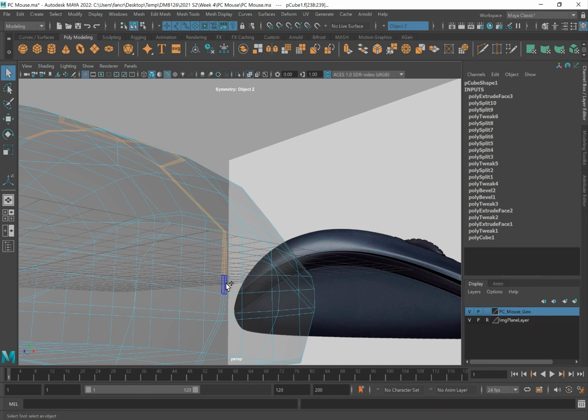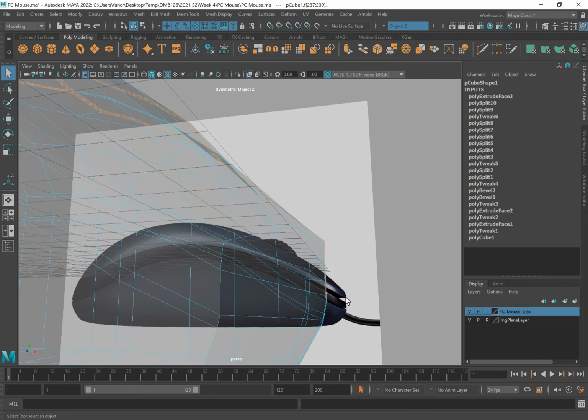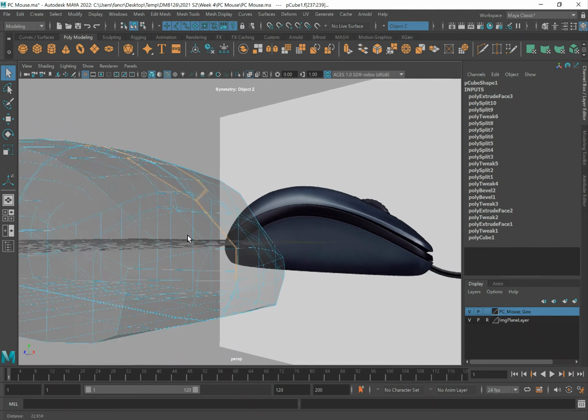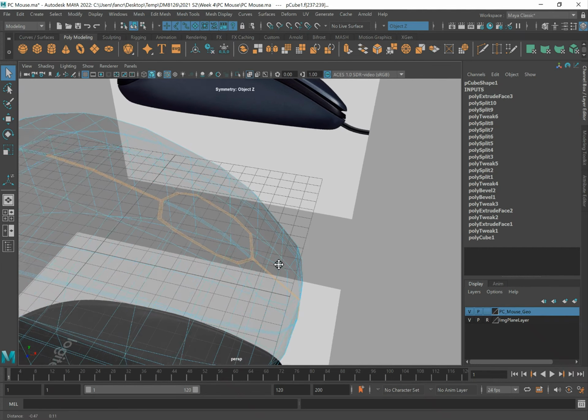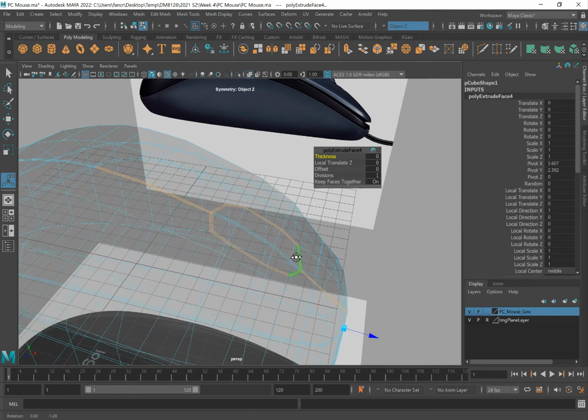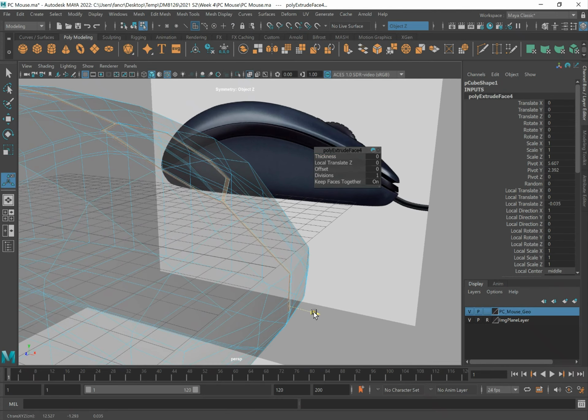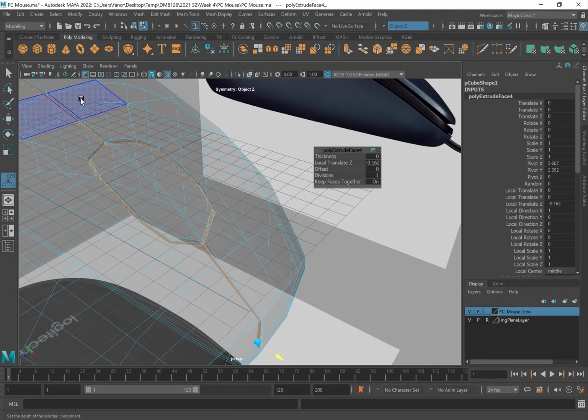So in fact, this would also be involved, since this is the thickness part where it's going to come in here. Okay, so with that selected, I'm going to hit my extrude, Control E, or again Shift right mouse button, extrude face, right? So I'm going to use this button here. So as you can tell, it starts to go inwards.